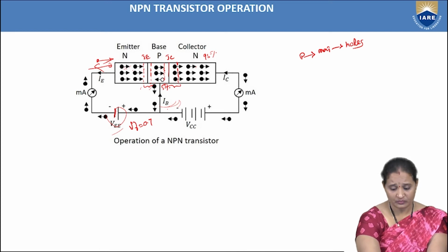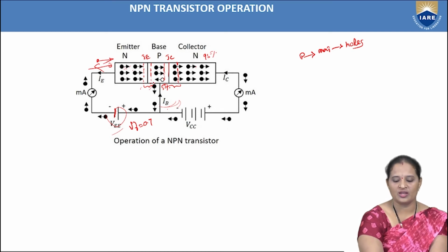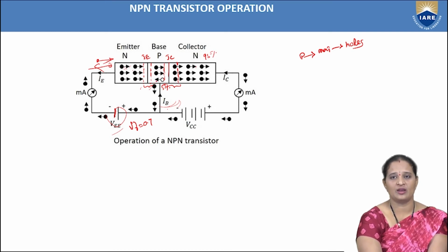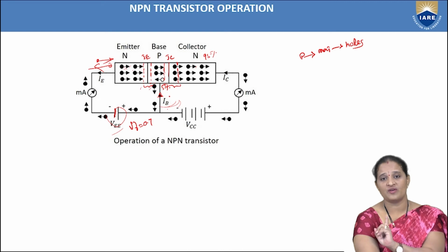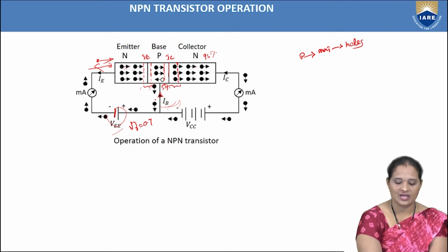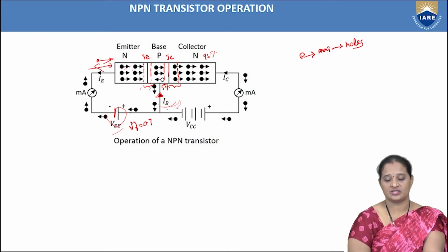Similarly, due to the recombination, some current is flowing here. In the p-type material, some electrons are present, which are minority charge carriers. They will be attracted by the positive terminal. As the electrons are moving in this direction, the current direction will be opposite to the direction of motion of electrons, so the current direction will be upwards.